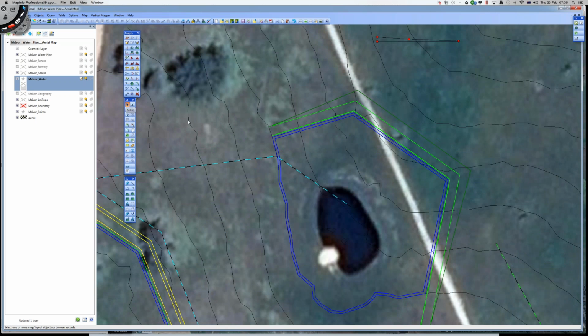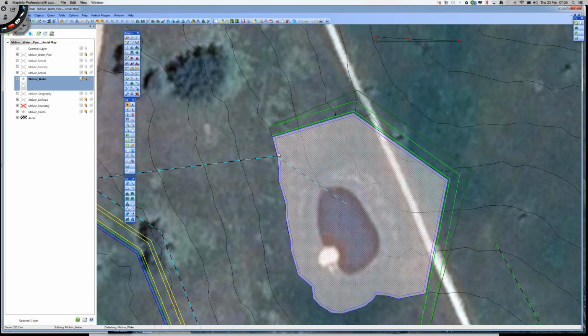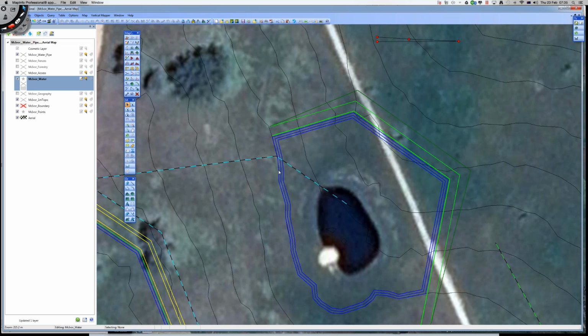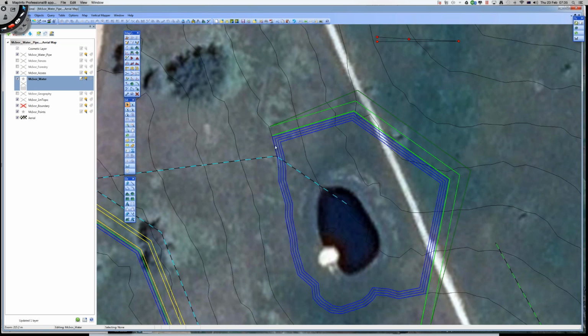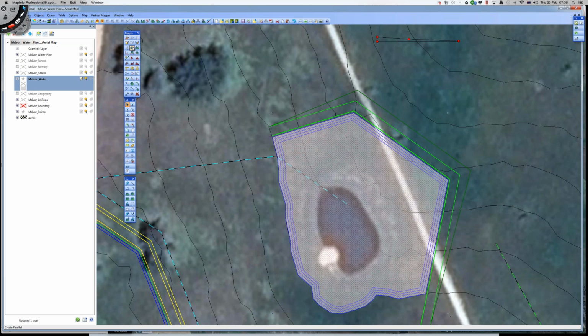So I didn't see which one was the right way around then. So we're going onto that outside one again, and I'm just going to take a punt with this and say it's to the right, and this time it's going to be 2 meters. Yep, I did it right. Okay, and then I'm going to go again. Now this dam we made 4 meters deep, so I'm going to go 3 and 4.